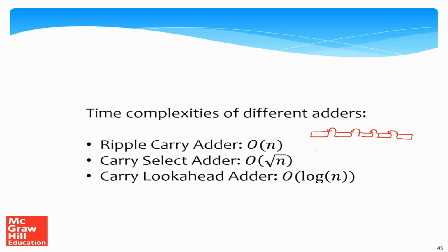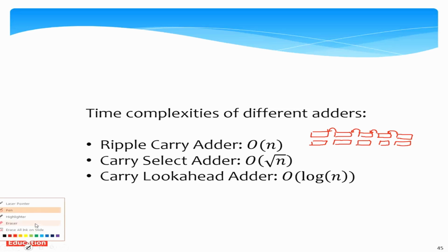What we did with the carry select adder is that we had slightly larger blocks, but in the first stage we actually computed two results, one with an input carry of 0, one with an input carry of 1. So we had two results. And so then what we did is that we quickly took a look at, so let me maybe clean this up slightly such that I can re-explain in a better way.